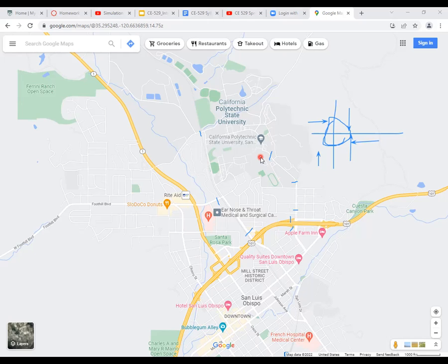And beyond that, you have to match what we call, sometimes, depending upon your application. Let's say you're really interested in safety level analysis and you want to be able to estimate the conflicts. Then you probably need to video record the data at a certain location and see if you're even capturing the headways correctly, whether the individual headway distribution is matching the real world or not. So it's all sort of context specific.